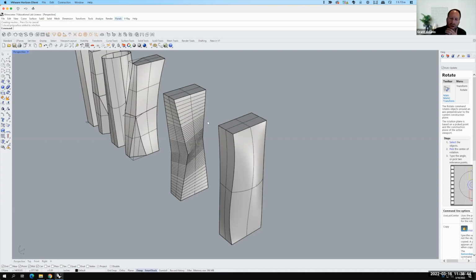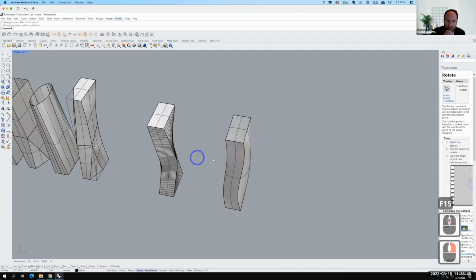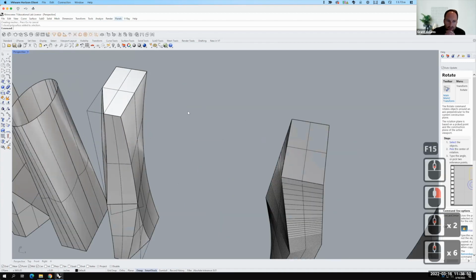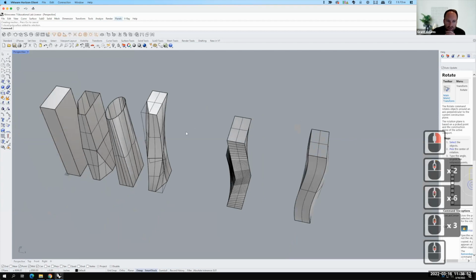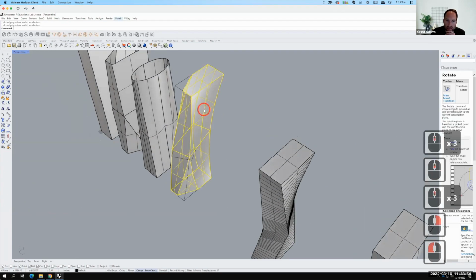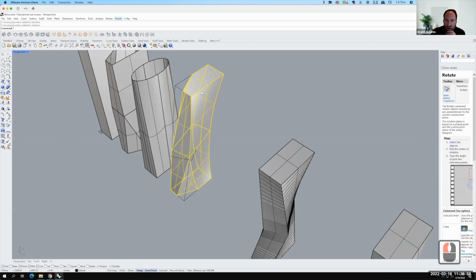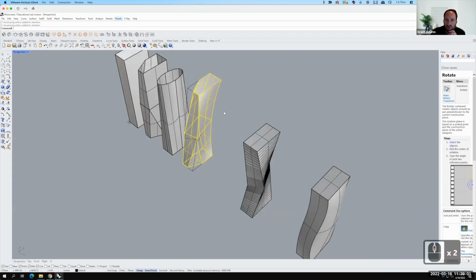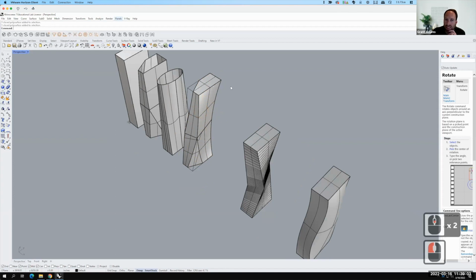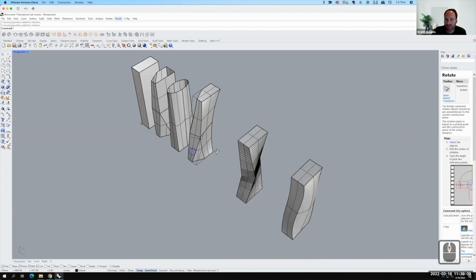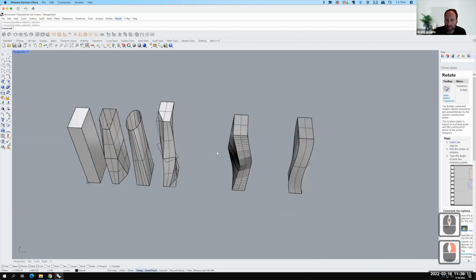When we have surfaces that don't curve in two directions, but curve in only one direction, essentially lofted surfaces, for example, this being a pretty good example, it's curving in this direction, but it's straight across. That is what's called a ruled surface, and that's something that we can build because at any one point across the curve, it's a straight segment. So we'll cover this when we get back into making unrollable surfaces.